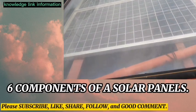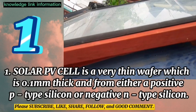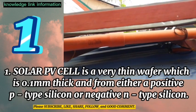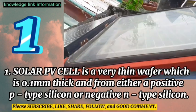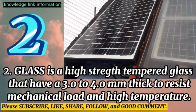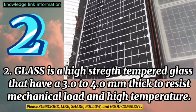Six components of a solar panel. Number 1, solar PV cells are very thin wafers, 0.1 mm thick, made from either positive P-type silicon or negative N-type silicon. Number 2, glass is a high-strength tempered glass that is 3.0 to 4.0 mm thick to resist mechanical load and high temperature.